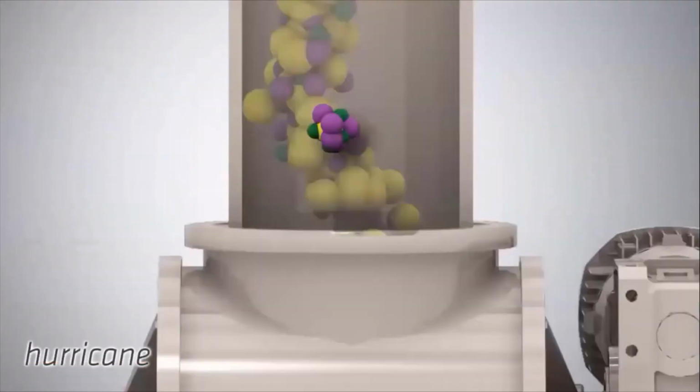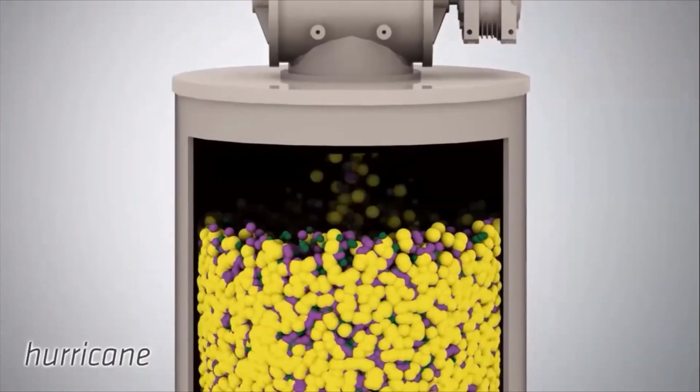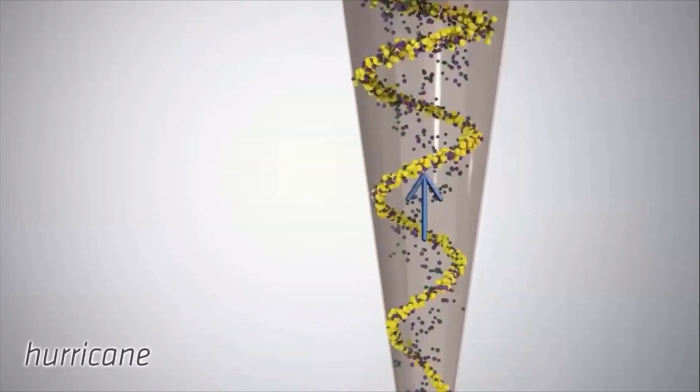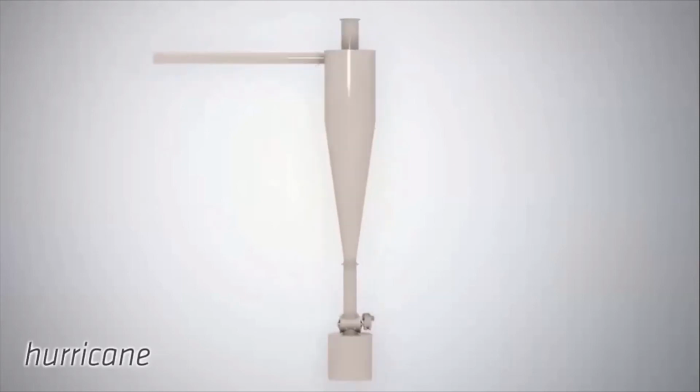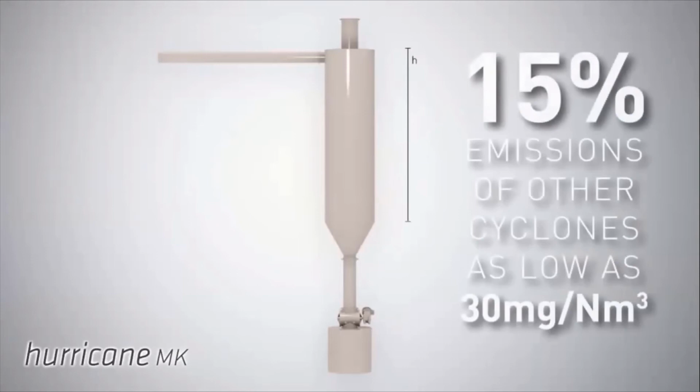In fact, the cyclone doesn't see as many small particles, but clustered particles with bigger dimensions and thus easier to collect. Agglomeration increases with wide particle size distributions, long residence times in the cyclone, and large inlet particle concentrations. Agglomeration is maximized with the new developed Hurricane MK cyclones. Emissions can be under 15% of those of other cyclones, being as low as 30 milligrams per normal cubic meter for many industrial processes.